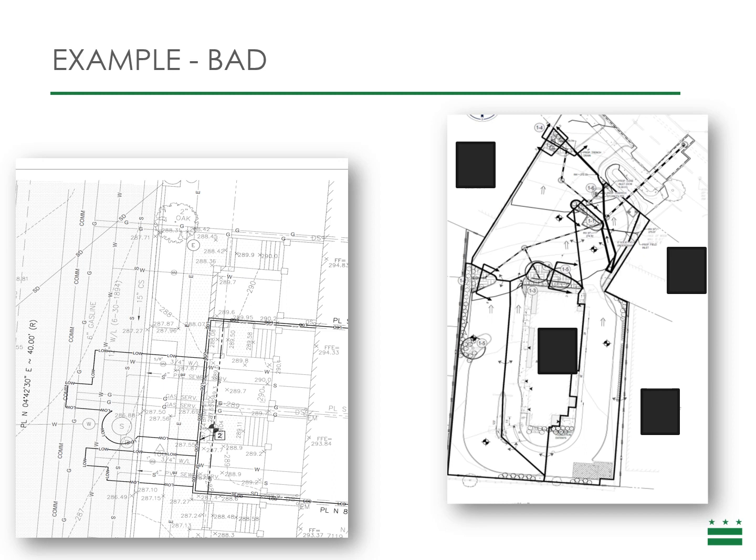In this example, it's the opposite. It's very difficult for a plan reviewer to understand what the lines are representing. For both of these plans, there are lines that are the same thickness and types that are not labeled or differentiated. So it's very difficult for a plan reviewer to know if the line is concrete, the line is water main pipe, or the line is an LOD. So having clearly defined lines and line types are very helpful for plan reviewers.